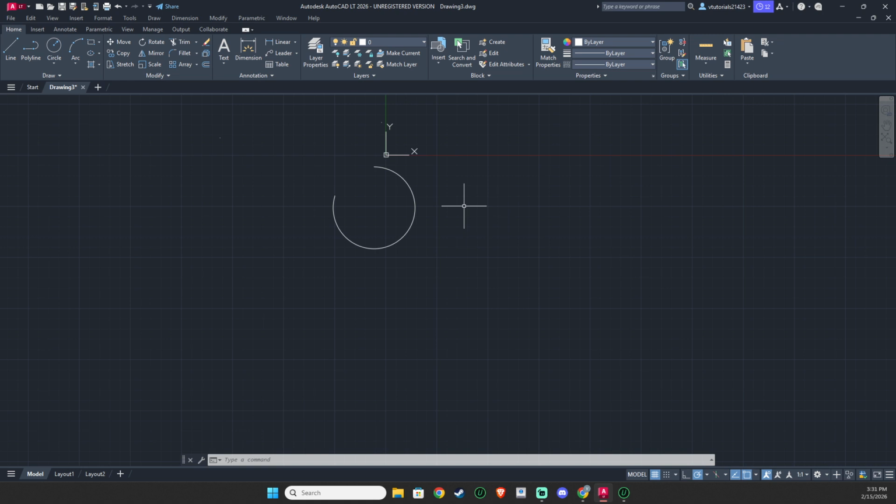That's it. You opened your drawing, started the arc command, set the start point, set the end point, and specified the radius to finish the arc. Practice with a few different radius values to see how the curvature changes. With this method, you get predictable results every time and a clean, professional curve where you need it.